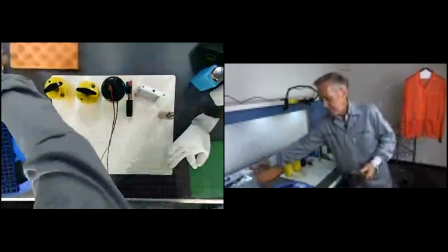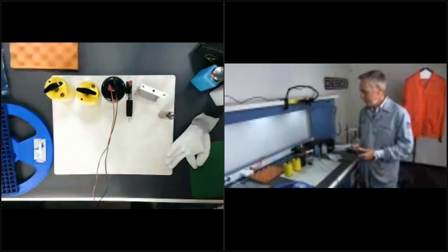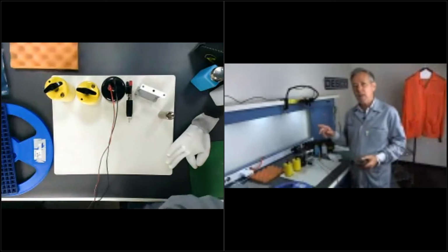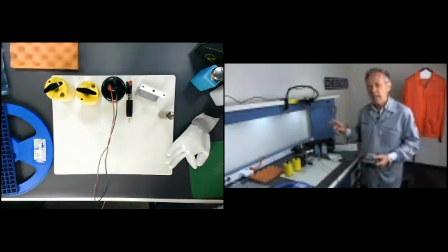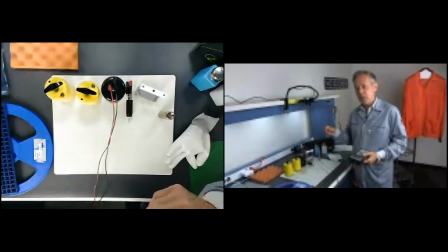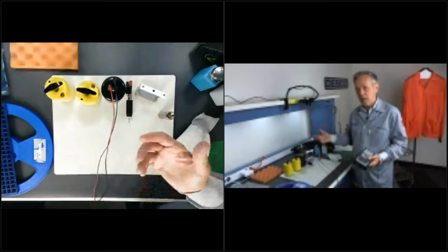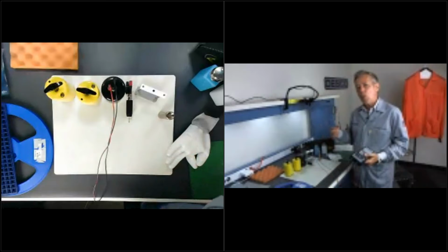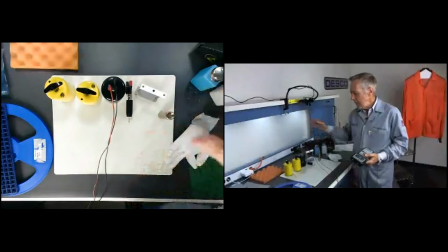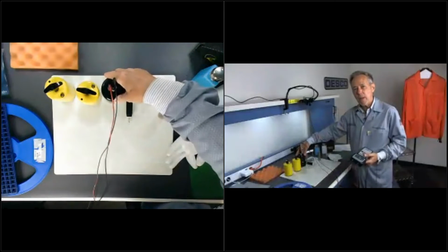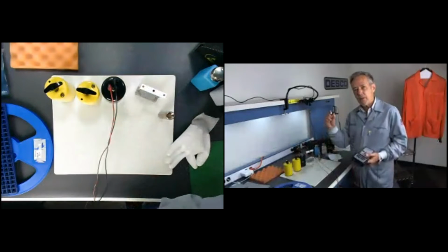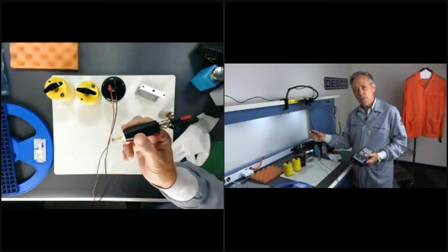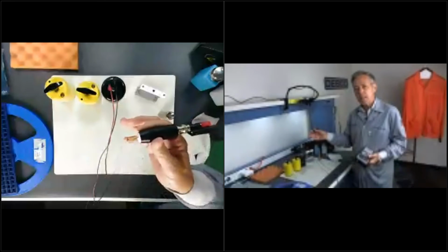Do you have any cutters or tweezers there? I don't, but there's a couple of different ways you need to test tools. One, if they should be grounded, if these are conductive tools like a cutter, plier, metal tweezer, etc. If I want to check the surface resistance of that tool, again, if I could fit my concentric ring probe on there, I could do that. If I had a very fine tip tweezer, I might use my 2-point probe to do that. So it's the same measurement.